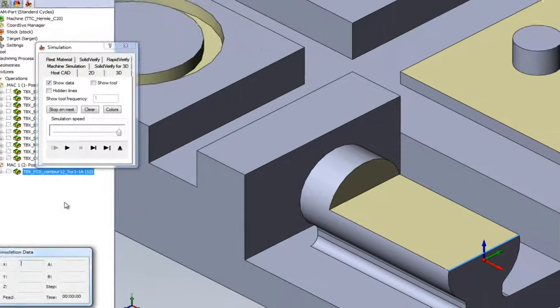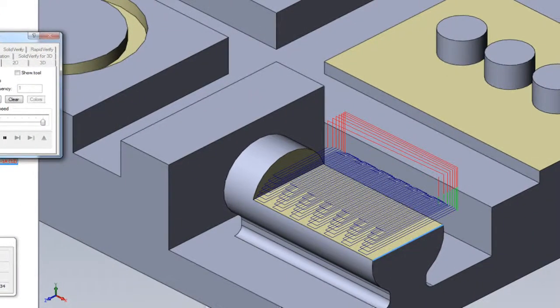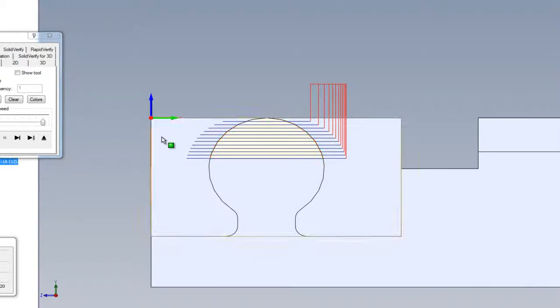Let's take a look at our simulation. As you can see, the deeper it goes onto the part itself, the longer the tool pass on each level. Basically cutting only the amount of material it actually has to work over. The length of the toolpath is automatically calculated according to the radius on that particular level each time. As you get further down, it gets wider and wider.